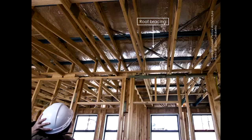So while you're going to draw the plans in your flipbook section, perhaps we're talking already about stage 5 and 6, make sure that you consider the bracing system that's added to that part. If you draw a stud wall and you see the stud wall in section here, but in elevation, in the background, you see there is another stud wall, perhaps that's also braced. So make sure that in your flipbook section assignments, you always represent what you see in section, but also what's visible in the background, all right? So make sure that you consider the way the building works in 3 dimensions.